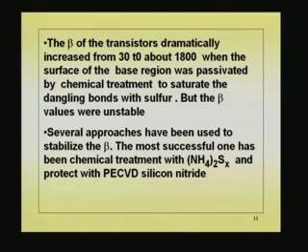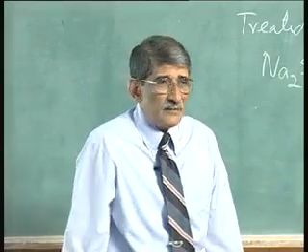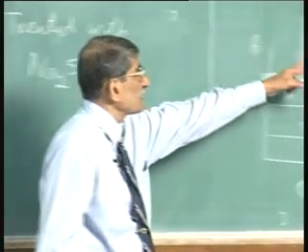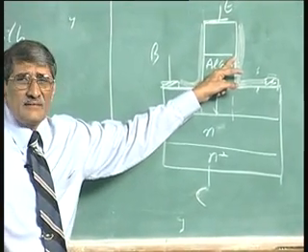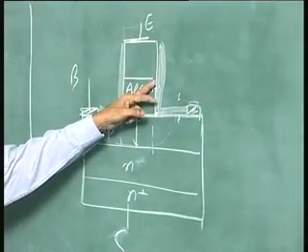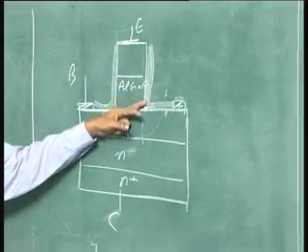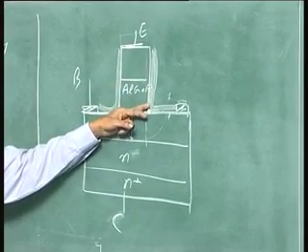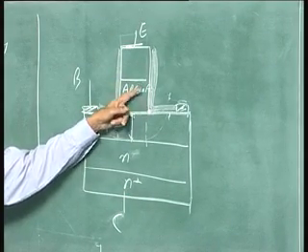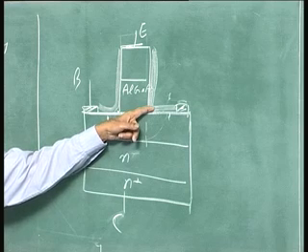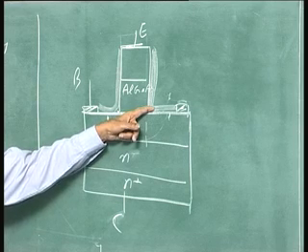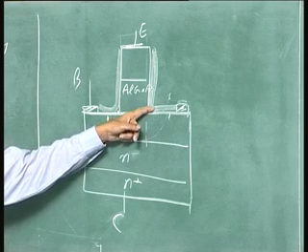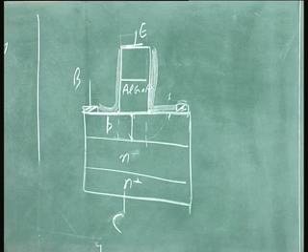Number two, the sodium sulfide layer on the surface gives rise to some leakage current across the junction. You do not like any sodium or potassium contamination. The sodium sulfide gives rise to leakage there. So, barring that leakage, the beta went up. To remove that sodium, it was dipped in water, and the whole thing went off.